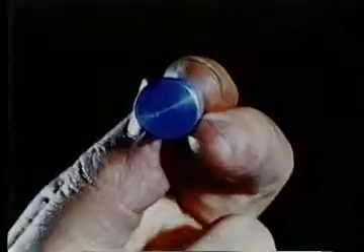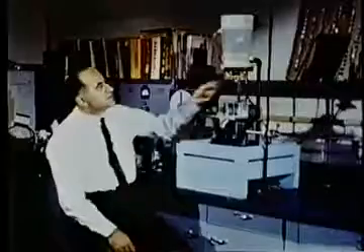To show you how quickly cavitation can cause damage, we will expose the surface of this aluminum button to a cavitating cloud. The cavitation will be produced in an alternating pressure field created by oscillating the specimen itself. The specimen is driven by this magnetostriction oscillator.